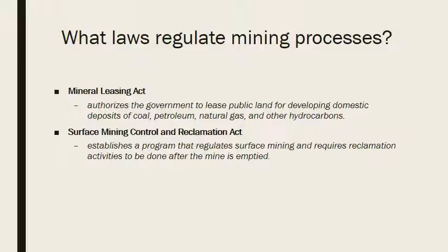One of the things that this law does is it tries to reduce the problems that come in after the mine is finished. It tries to remediate the area by requiring the filling in of an open pit, the coverage of an area mine, the planting of trees, and mitigating activities to reduce the problem of acid drainage. And this is when water infiltrates a mine, carries through the acidic salts or the acidic compounds from the mining process, and carries those into nearby bodies of water. So the Surface Mining Control and Reclamation Act is really there to require mining companies to fix the damage that they cause as they are extracting this resource.